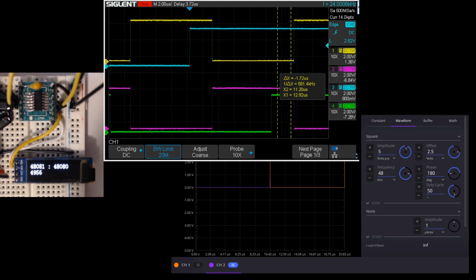So you can see just by the scope display that we really are spending most of the time servicing interrupts when there's 48,000 interrupts per second per channel. So that's about the limit we can do with these standard Arduino interrupts.